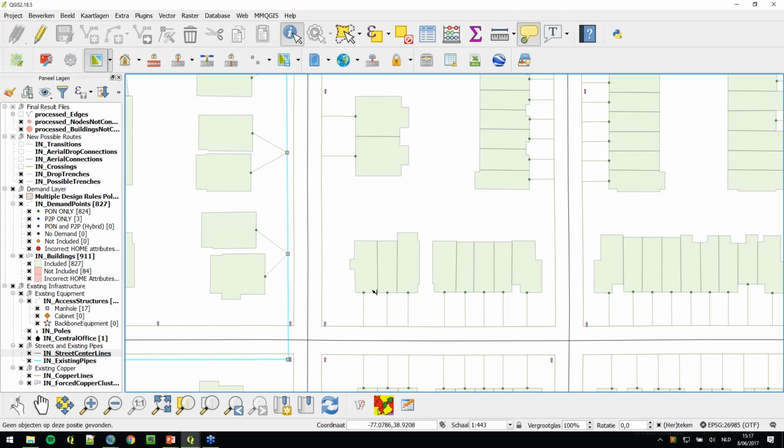So you can choose whether it should first drop to an existing manhole or an existing pipe, or to a trench, so that these lead-ins are created automatically. Here we did not drop to the pipes, but created a drop to the manhole, which is the preferred option. And there's also a way to set the cutoff distance for every single lead-in.